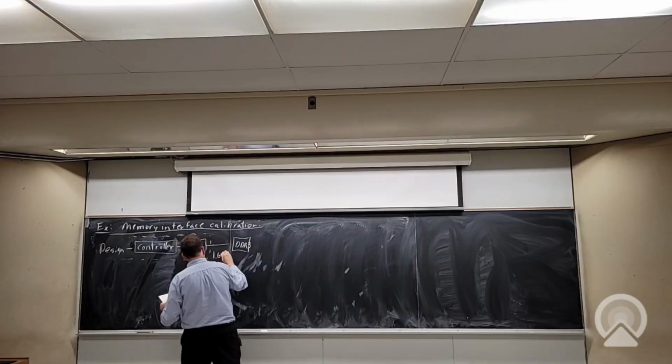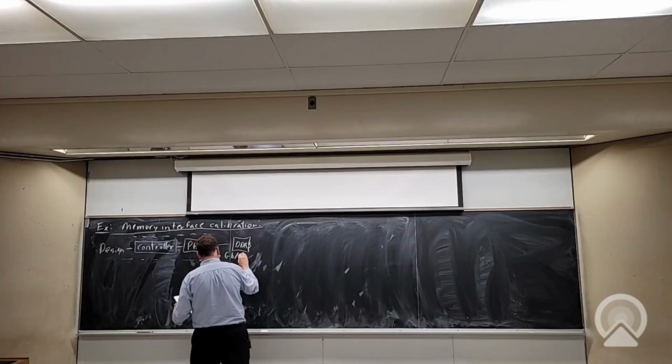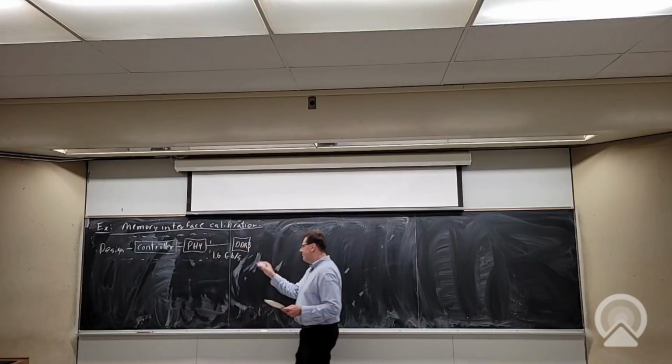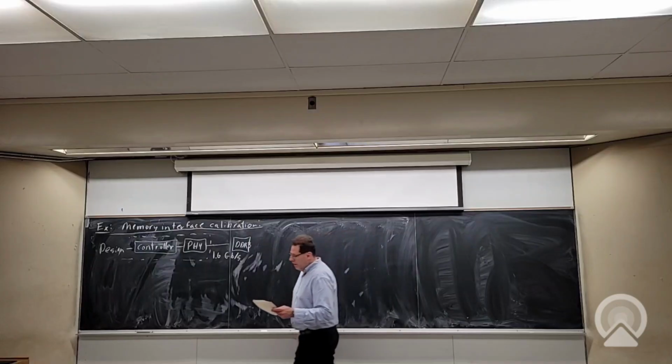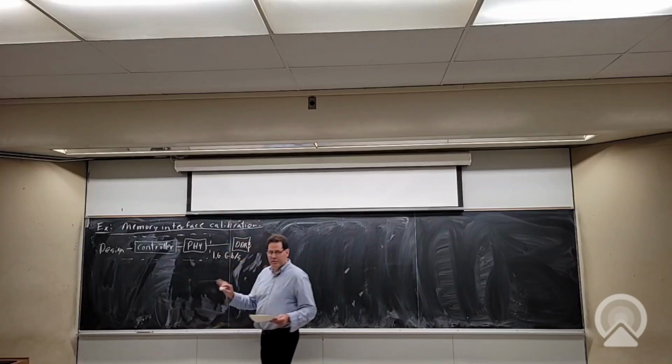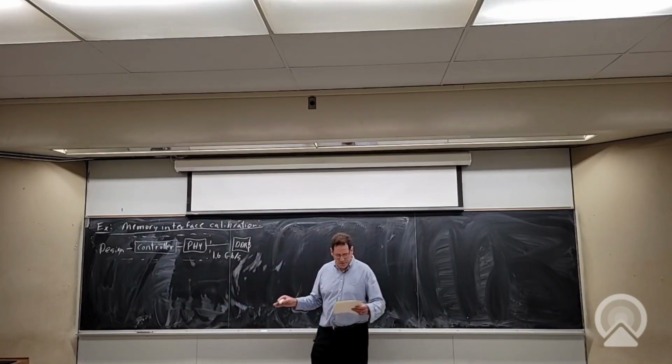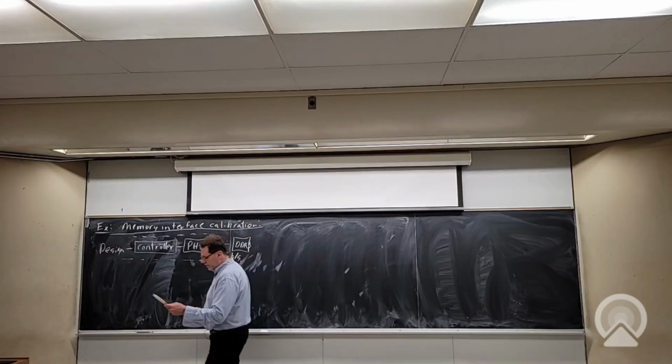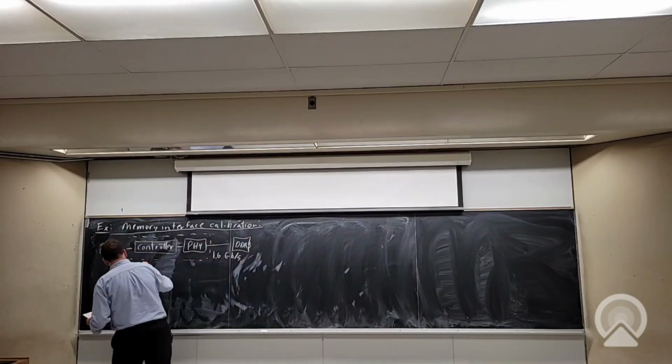It is talking to it at 1.6 gigabits per second. So the time window between data is only about 60 picoseconds. So pretty fast, pretty easy to get wrong. All of this part is on the FPGA.